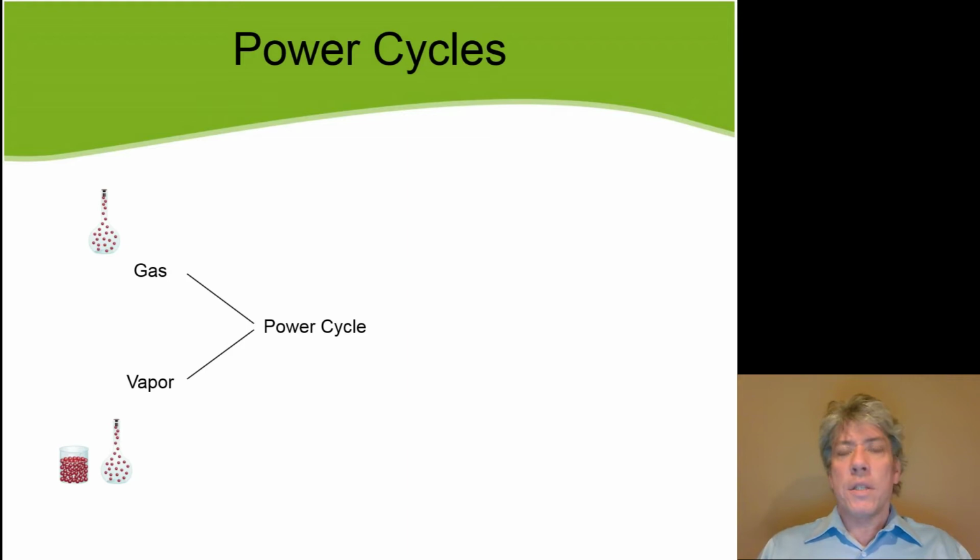So what is the working fluid? What literally pushes the piston down? What applies a force through a distance? Well, it's air. You might say, well, why do I need the gasoline? Well, think about it. The air comes into the engine, and you know that more air comes in by mass than gasoline. The way you know that is probably somewhere along the way in a chemistry class that you've heard that the stoichiometric ratio is 14 or so to 1 for air versus gasoline.